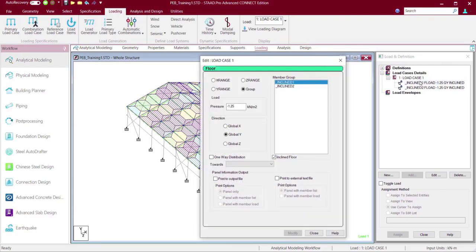But here in this steel section, you just consider the metal sheet which is resting actually on the purlins, right? It is not resting on the flanges of the tapered beam. So basically, they don't behave like a typical two-way slab system. Rather, they will behave like a one-way slab. So you can rather select the one-way option.